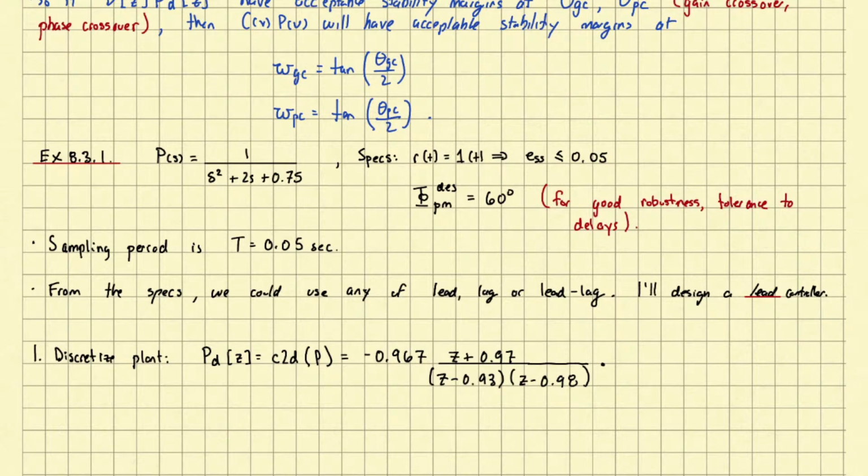Or in this case, it would only need one in that case, right? Because it doesn't have to be conjugate, but it's the same. It's the exact same idea. It's a point on the circle at -1. It sort of corresponds, if you want to think about it, to the smallest period you can have in discrete time, right? You have a value, the next time step you have a different value, and the next time step you're back to your original value. So your period is two discrete time steps. You can't exhibit any sort of discrete time signal with a smaller period. All right, I gotta go, so I'll see you guys next time.